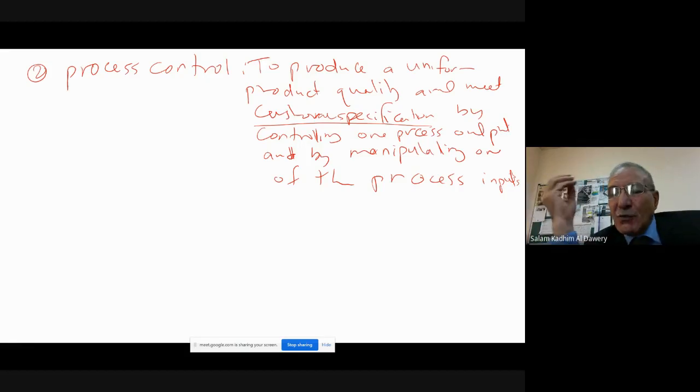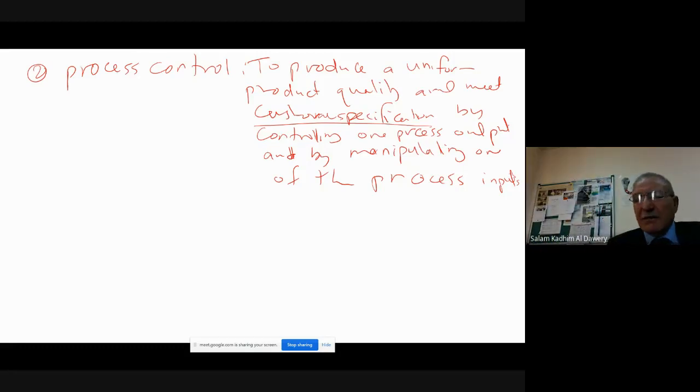How do you reduce it? You have to increase the flow rate, or you have to add another cooling media to cool it down. Because if the temperature from the heat exchanger increases, that might go to the distillation column, or the reactor, or another process. So you have to control that particular issue.